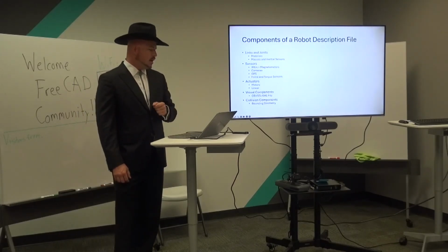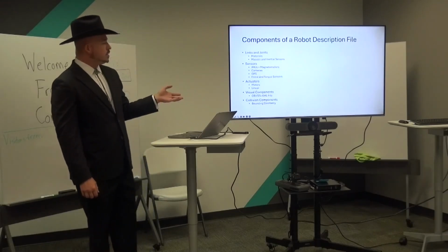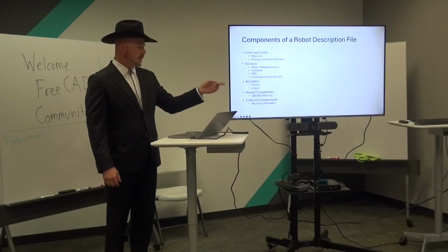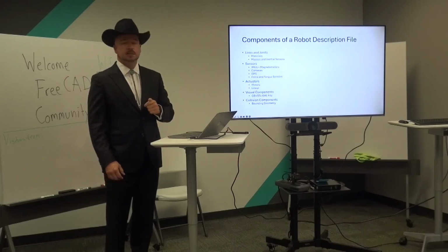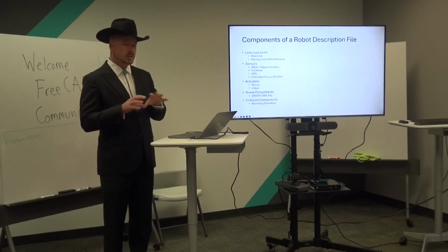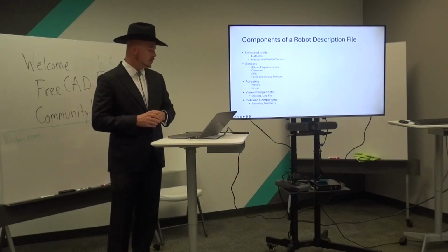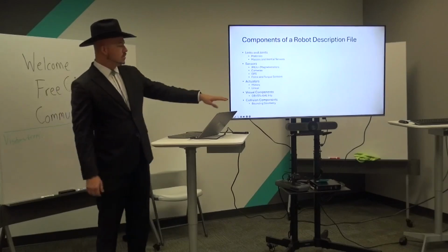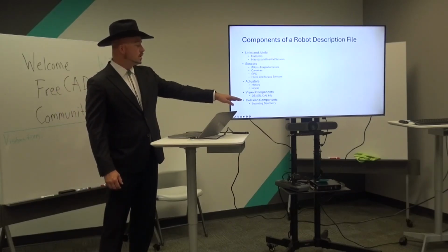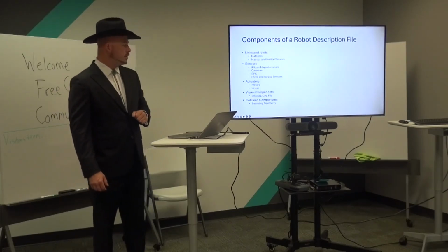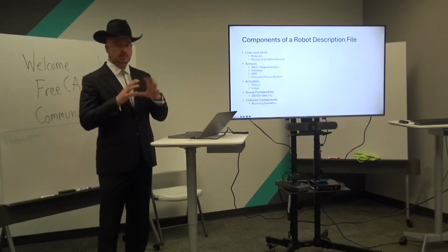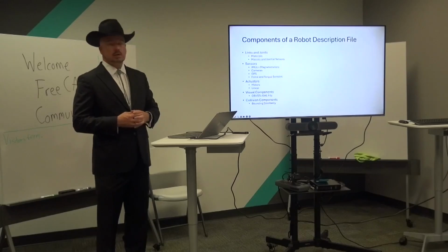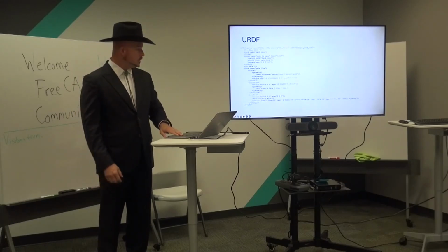You add in your visual components, and you can describe this using the different file formats, the OBJ, STL, or Collada. But you could also describe it in general shapes as well. And then the collision components, and so typically you use a less accurate form of the visual components, so you do a convex hull optimization, import that, so you have less computation on the physics aspects of it.